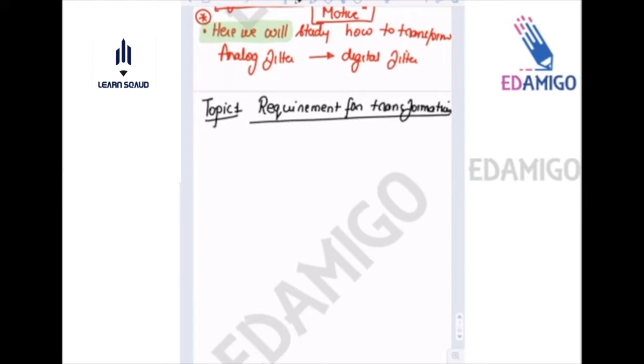Okay. Now, what will be given to us is the analog filter, and always the analog filter will be given in the transfer function format. So the transfer function of the analog filter is Y(s) upon X(s), and it is given in the format summation k equals 0 to m d_k s to the power k divided by summation k equals 0 to n a_k s to the power k. So this is the transfer function. Now if we convert this transfer function into an equation, it can be written like this also.